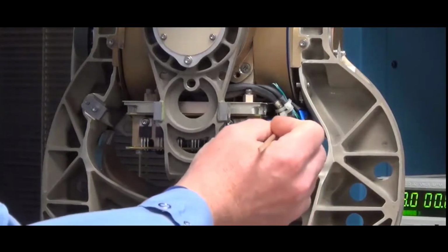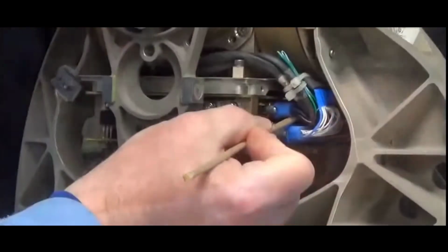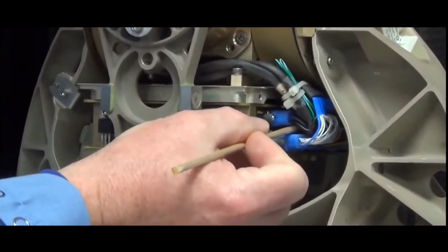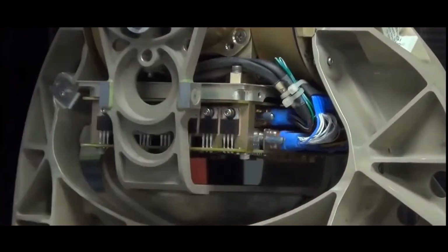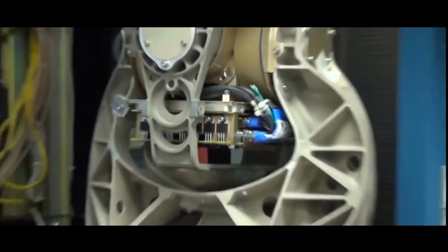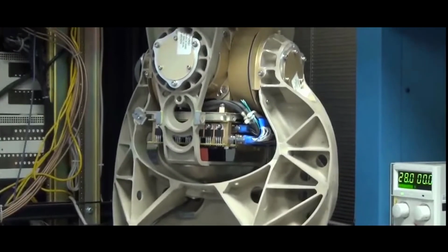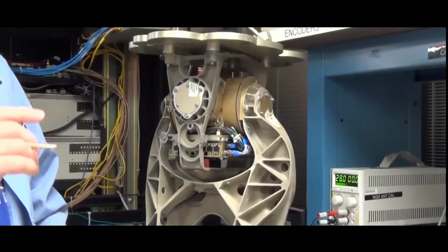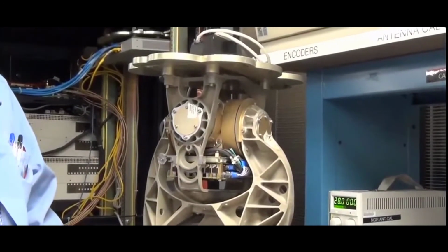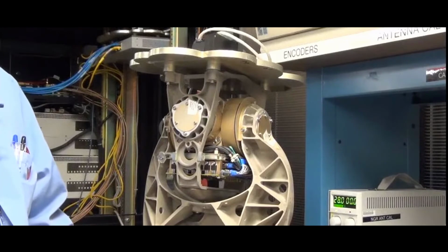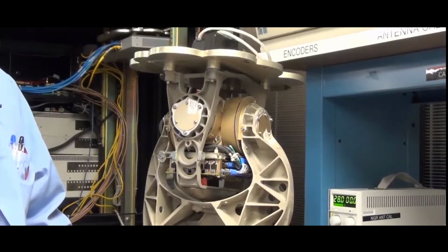So gently manipulate the wires and the connector. If you see it kind of move off on its own, and it just has to move slightly on its own, if you see it move once, you have a bad connector pin, and you need to replace them. And if you replace one, replace all the resolver pins, because we have found that if we have one, we usually have more than one. And that pretty much concludes troubleshooting and how to find a bad resolver pin.